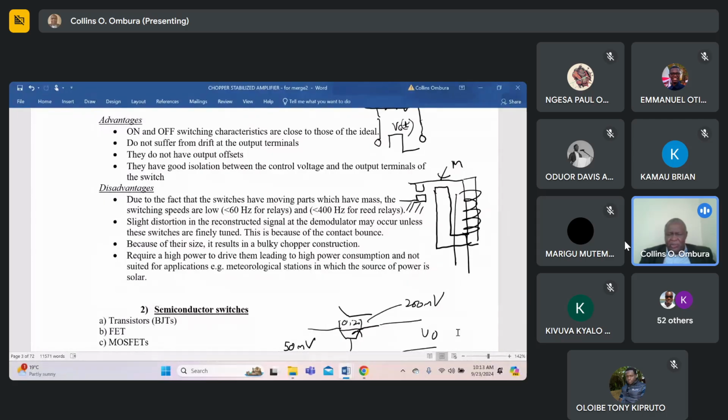For most of our problems, let us consider the chopping frequency to be maybe a square wave. If you do the same for the square wave, you find that you tend to get the fundamental frequency, third harmonic, fifth harmonic, seventh harmonic, all the odd harmonics, and the change of the amplitudes. So the actual amplitudes can be obtained by the convolution theorem. That's the field of telecoms, which I don't want to go into here, but you should know it.